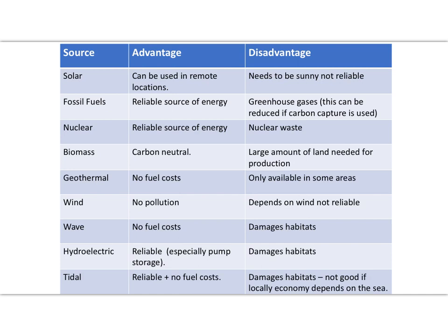The source we're going to look at is tidal. Tidal barrages work by having an area of the sea blocked off, so the sea will come in, the water will go past the gate, which you can then lower if you want to, and then you can hold the water behind these gates, and when you raise the gates up, the water will flow out, and that will flow past your turbines, which it will turn. The turbines will then turn a generator, and that will produce electricity.